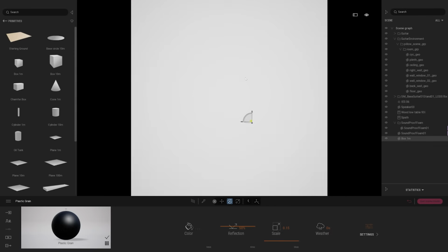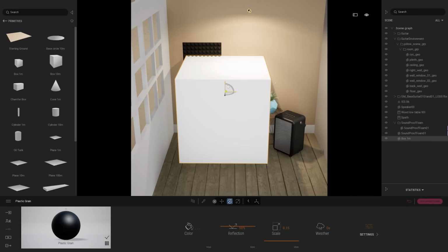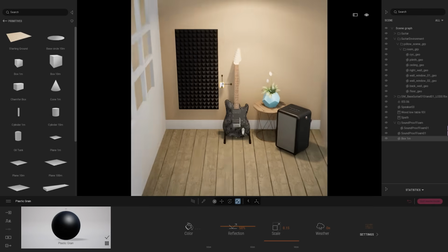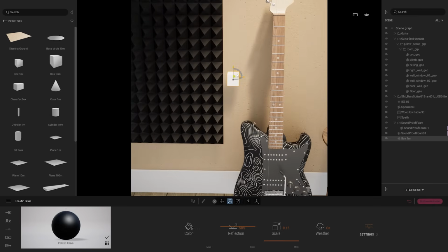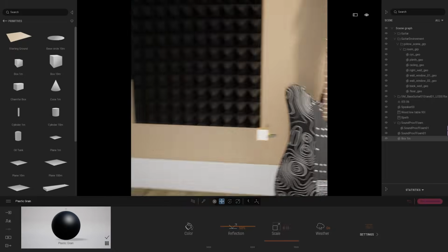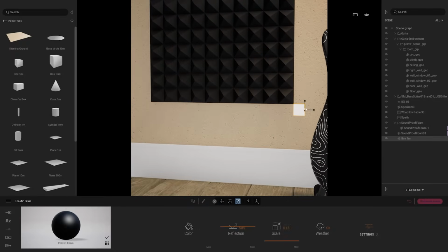So of course, I could come back to my modeling tool and actually model the wood framing, but in our case, I'm a bit lazy, so I want to do that directly inside Twinmotion. So here I'm just using a basic box that I'm scaling down. I'm just going to turn that facing that way, making it a tiny bit smaller. I'm going to align that just on the side like that, and I'm going to scale that in that direction.